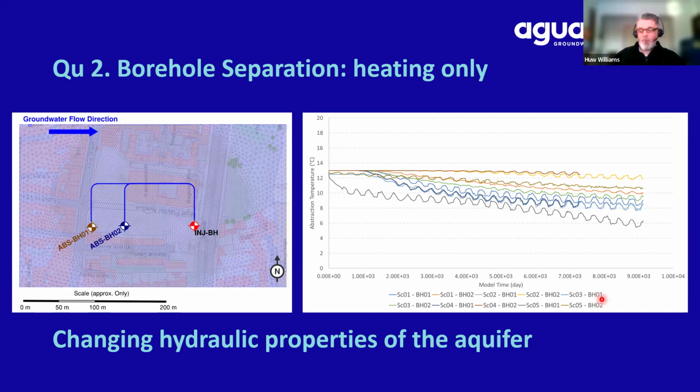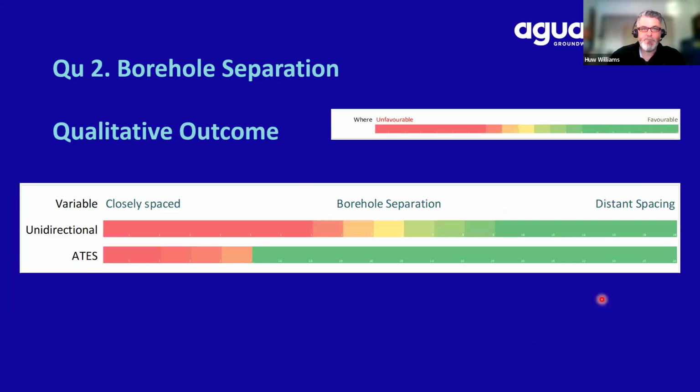The separation that you can have depends on the aquifer properties. Now, obviously, aquifer properties are something that we don't know until we've drilled at a particular point. So up until a certain point in a project, we are estimating what those will be. So to try and answer some Goldilocks questions, where is our favourable zone in green versus unfavourable in red, and everything in between?